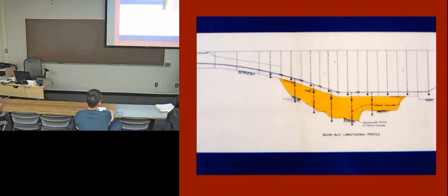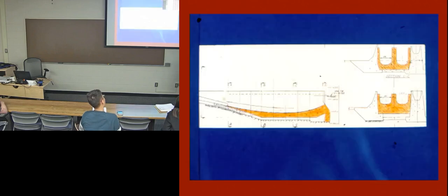So repair was implemented, and the stilling basin was tied down with rock anchors. These anchors went down into bedrock and were pre-tensioned to hold the slabs in place. The next time the reservoir got to a high enough elevation, these were torn out again. Just blasted out like before.